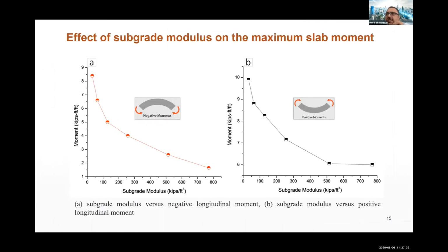We also tried, because based on the observation, we found that most of these bus pads in Baltimore City suffer from poor subgrade compaction. Once they try to replace the flexible pavement with the rigid pavement, they have to cut out the asphalt and then compact that part of the soil, but that compaction is not a perfect compaction.